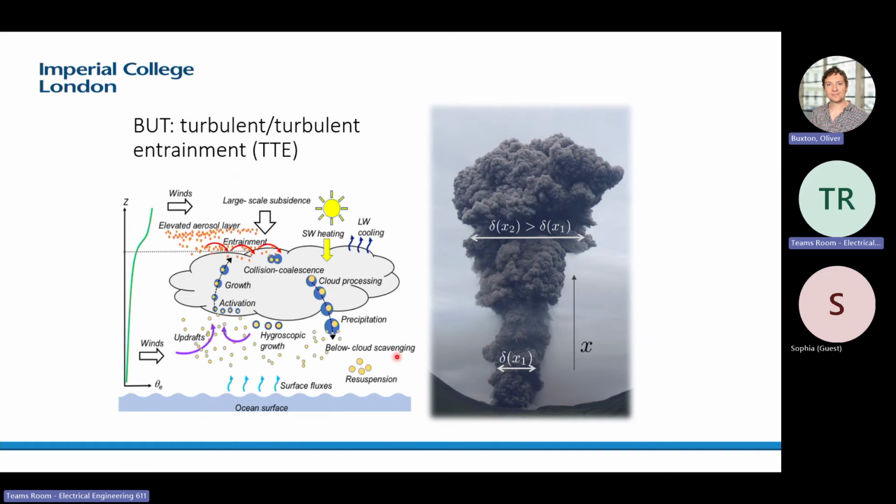However, the situation for wind turbines, and indeed volcanoes and clouds, is complicated by the fact that they don't spread into a non-turbulent background. The atmospheric boundary layer is itself turbulent, meaning that I have vorticity in the background as well as vorticity within the primary flow itself that is spreading. So I can't simply rely on identifying this interface by using a vanishingly small threshold on vorticity magnitude. So we need to come up with an alternative way of doing that.